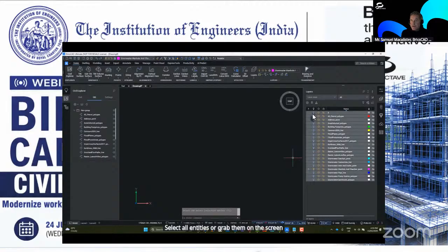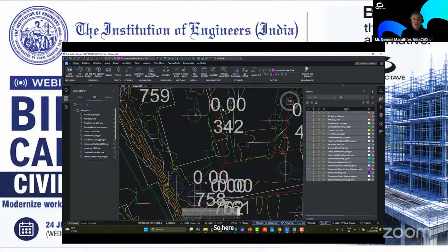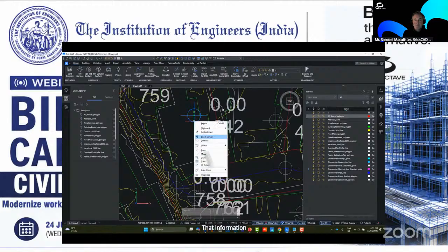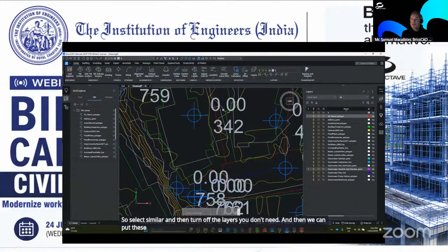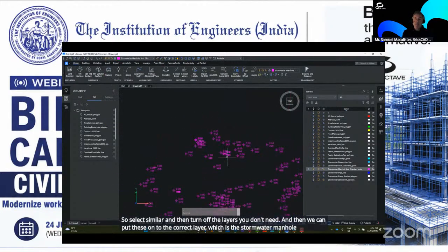and then make sure they're on the right layer. So here, these by default have gone on to my layer 0. Not a problem inside a CAD application. Just simply isolate that information. So select similar and then turn off the layers you don't need. And then we can put these onto the correct layer, which is the stormwater, manhole, and chamber pot.